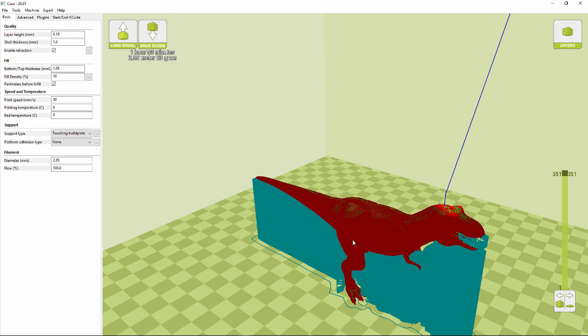And then it's simply making sure that before you start the print, you're setting the base plate and the tool tip temperatures prior to starting the print itself. So double check what's recommended, set the base plate temperature, set the nozzle temperature, and then once those things are actually at temperature, which usually only takes a minute or two, start the print from the G-code.